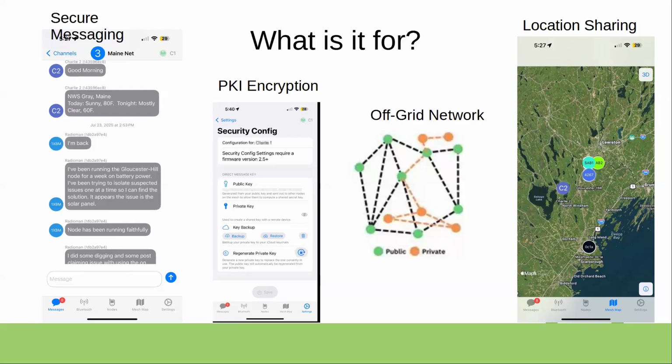And we're only going to hit the wave tops of what this can do. Most of the stuff is going to be on frequency slot 20, but there's a bunch of different frequency slots along the band here. This is the 900 megahertz ISM band, so there's a decent amount of bandwidth available across there. And most everything that you're going to see is on the primary channel, channel 20.